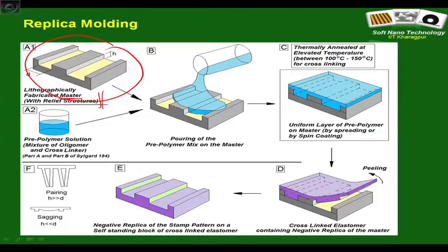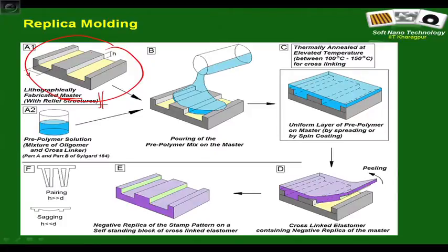Well, you can use either focused ion beam or electron beam lithography to create these masters, but you can also use photolithography itself to create this master, maybe a patterned photoresist layer or an etched barrier layer. You do not go all the way up to the doping and all that, but that itself serves the purpose of your master. What is the advantage of soft lithography? That is something we will see right now.